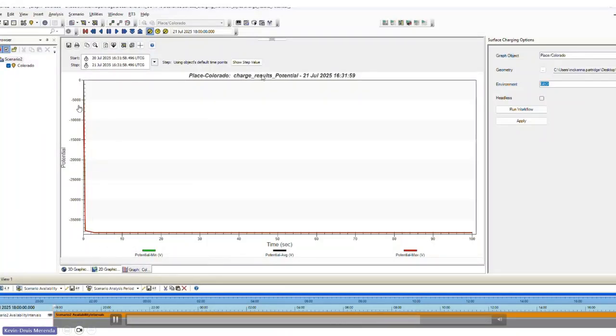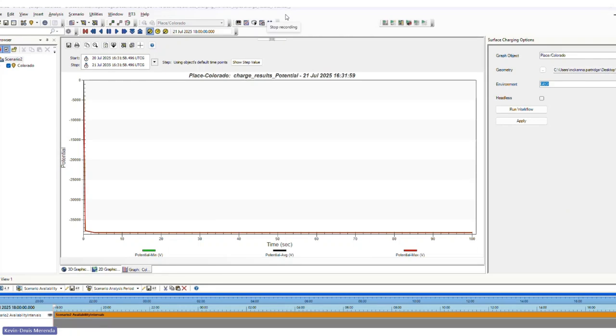And so you can make a sense. Usually the assessment for these simulations is looking at the potential between one surface and the other. In this case, everything is in aluminum, and so everything is charging to the same level. But if you have different materials at the surface, then you wouldn't get that same result. You may have a different potential for one material on one surface and another. And that differential voltage is what we want to minimize to make sure that we don't actually get a risk of discharge. And so we are shielding ourselves in some way from the space environment by making sure that we choose proper materials at the surface, or proper spacing between surfaces that have materials that are dielectric or conductive.